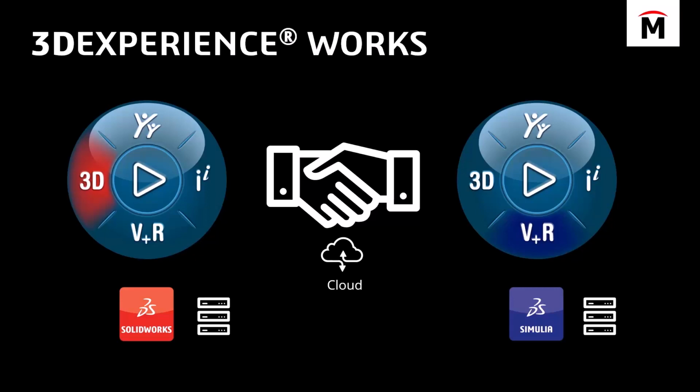Of course, all SOLIDWORKS installs locally, and big simulation softwares, they're also going to install locally, but we need some data translation in between. And since 3DEXPERIENCE provides us cloud data management, it does that transaction for us. We can simply save our files into it, open them up in another piece of software, yet we're still parametrically connected. We can make a change in SOLIDWORKS, rerun our simulation with that design change. We could do design of experiments iterations or optimizations this way, iteratively improving designs, staying connected the way you expect in SOLIDWORKS, even though we're in two different simulation packages.